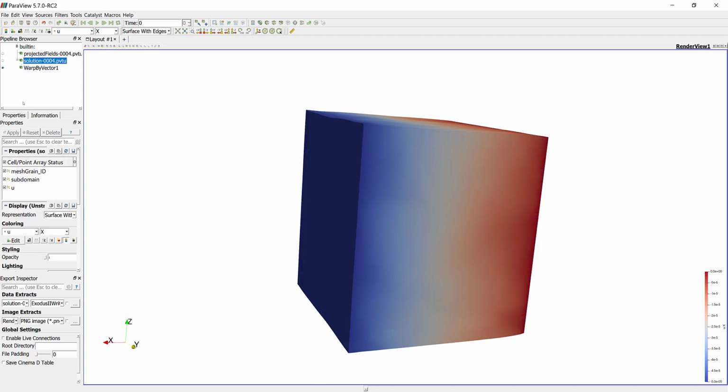This is really good for the initial visualization, but what if you want to actually process this data, or process other data like the stress or strain at each integration point throughout the body? Then we need to go to the next level of outputs, quadrature outputs. What if you want to have the stress or strain or any other variables for each quadrature point? Then we need to modify the parameter input file and add 2 lines to it.